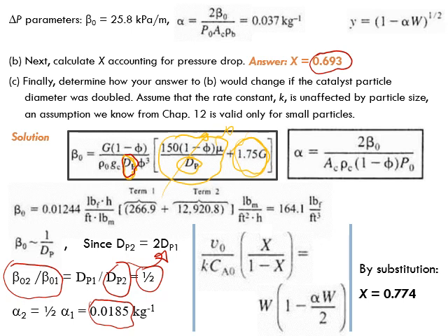the particle size. So we get higher conversion, but of course, still the conversion is lower than what we could have got if there was no pressure drop, which was around, I think, 82%. Was it 82%? Okay, but of course we cannot avoid pressure drop totally because we have a packed bed reactor.